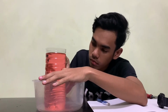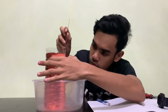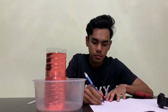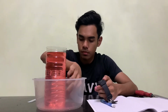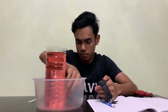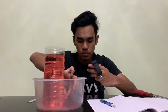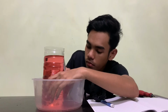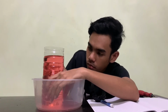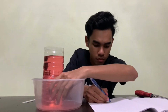Measure and record the initial height of the water level from the orifice. Ready the stopwatch. And then let the water flow out and measure the height of the water level every 5 seconds.